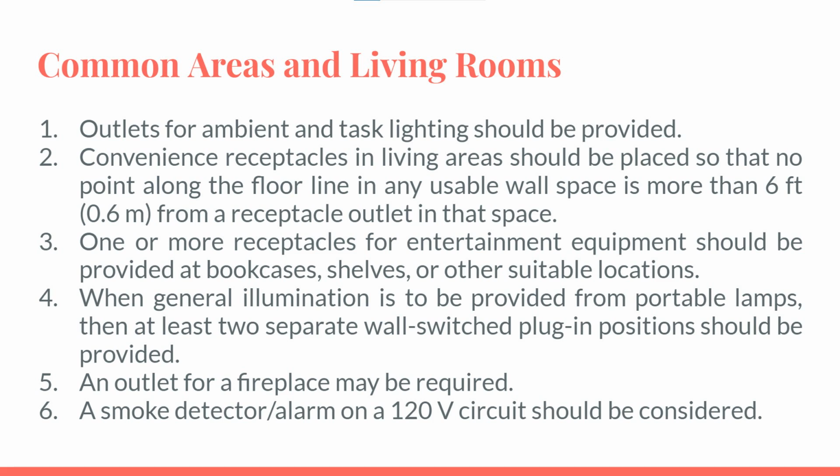Fourth, when general illumination is to be provided from portable lamps, then at least 2 separate wall switch plugged-in positions should be provided. This can be provided with two switch regular duplex receptacles or one switch plugged-in position in each of two split receptacle outlets. Fifth, an outlet for a fireplace may be required. Sixth, a smoke detector or alarm on a 120-volt circuit should be considered.